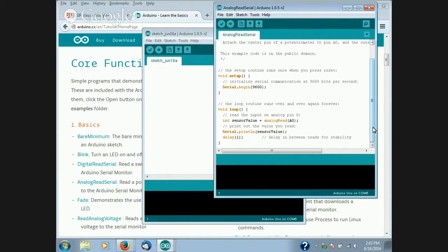So that means building that relay driver, picking relays to order, and getting one Arduino with just weather sensors working and producing a telemetry data frame. And if the TEC guys are ready, you can add their bit stream to the telemetry data frame.